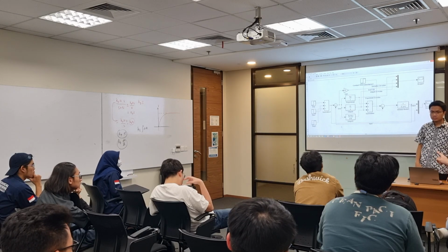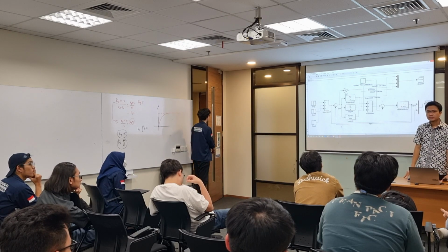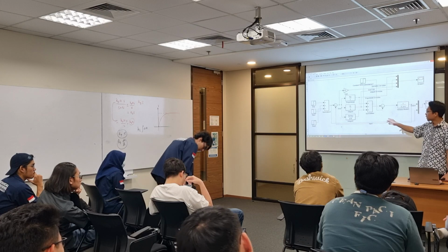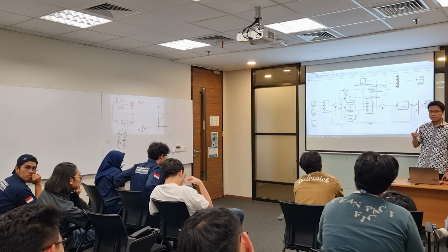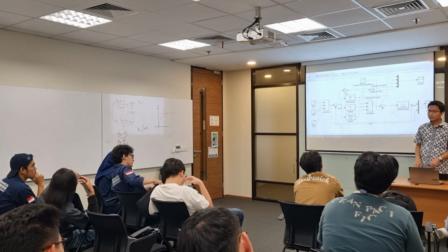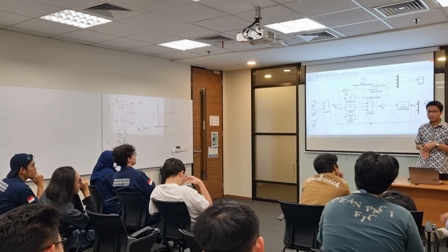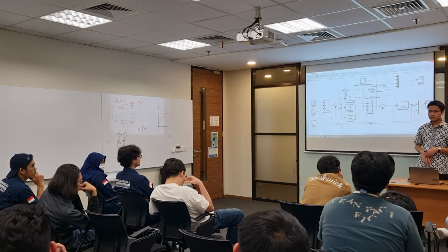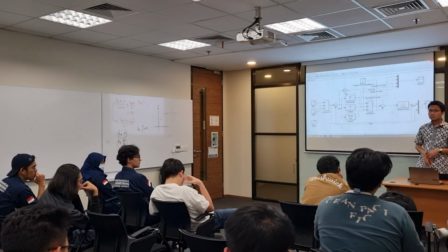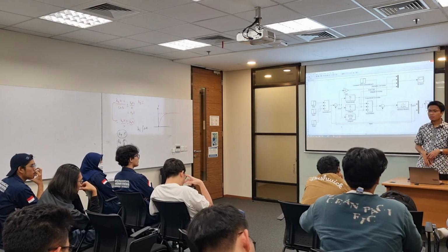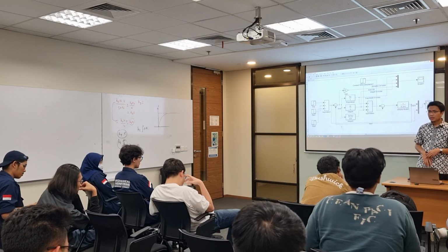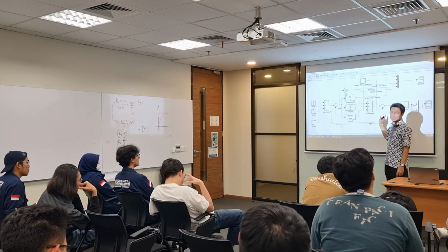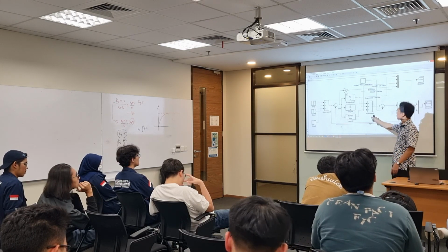Say that I remove the integral part. Does it affect it? Yes, it will affect. If you remove the integral part, then the steady state error will not be 0, so you cannot reach the desired value. There will still be error. Yes, of course, it changes. What we're looking at in the proportional, integral and derivative is the output of this control system into the plant. It's the control signal to the plant.